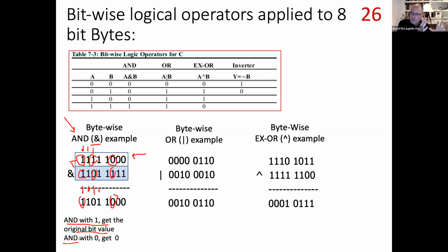So this is something we have to put into our toolkit. What we're driving toward is some bit level capability that will allow us to go in, mask out the other bits, and just decide whether we want to turn a particular bit in one of these registers high or low, or toggle it or something else. Okay, so that was the AND.